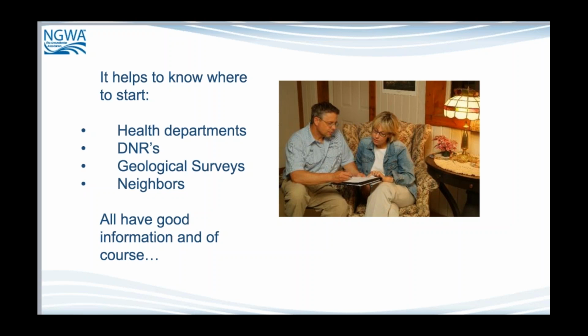Your neighbors are a good source, but one thing that we always talk about as drillers is that your memory is never as good as a good record. So even if your neighbor swears up and down that their well is 100 feet deep and it makes more water than anybody's ever seen, it's a good idea, but you don't always trust it until you see the actual record or the actual individual who drilled it and what they have to say, because some people's memories are just not quite the best. But in lack of other resources, your neighbors are a good supply.